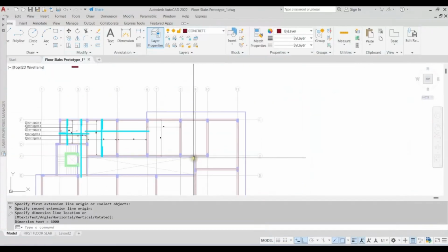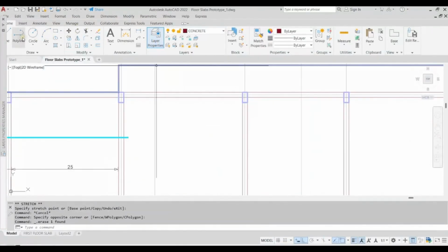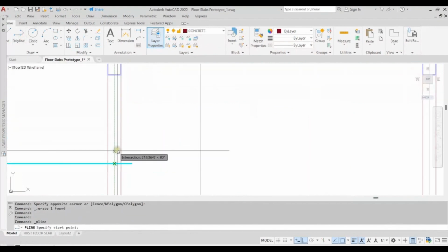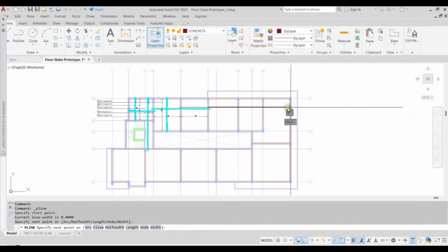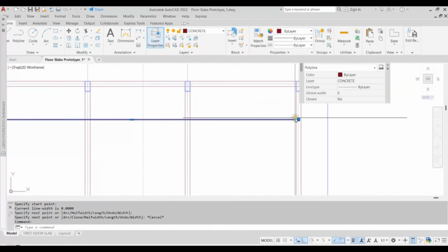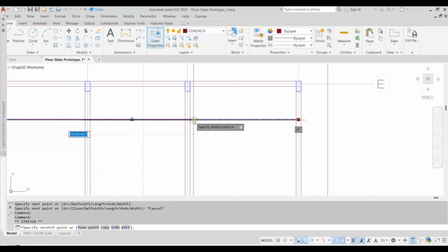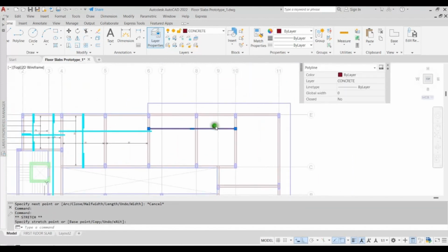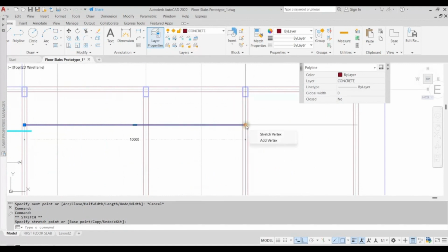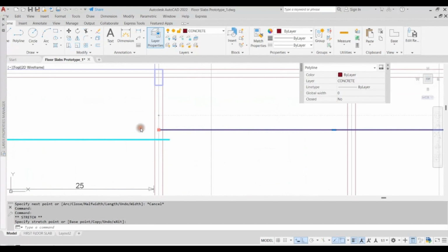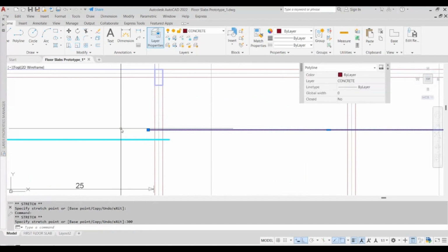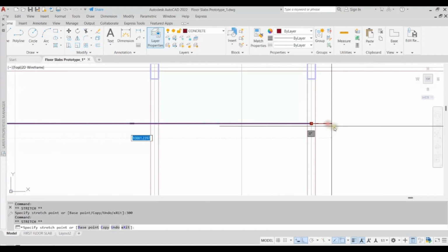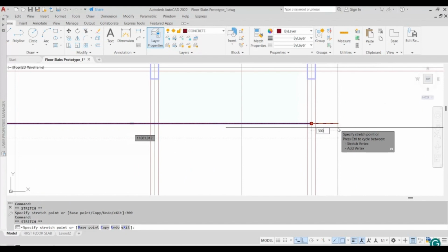So we'll go back. What we'll do is to implement what we have designed. So start from here, and then let's say we'll get to this end. But let's confirm, this is more than 12 meters. So we have to shorten it to this point. And then we check. This is 10 meters, which is okay. So the next thing, we extend this by 300 as usual. And we extend this by 300.